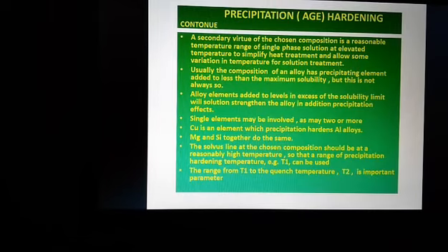A secondary virtue of the chosen composition is a reasonable temperature range of the single phase solution at elevated temperature to simplify heat treatment and allow some variation in temperature for solution treatment.